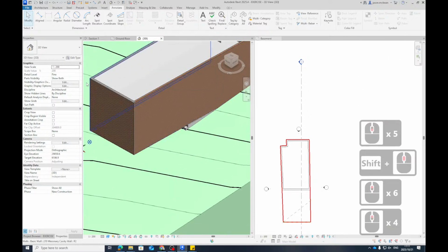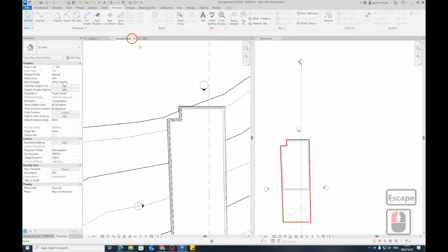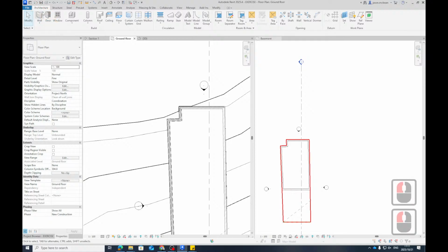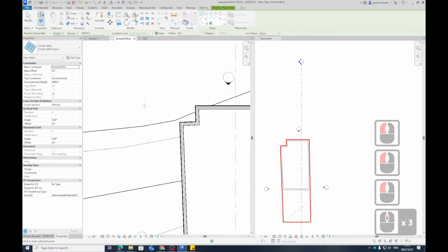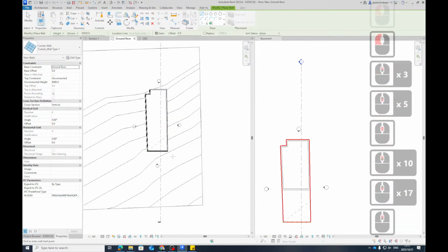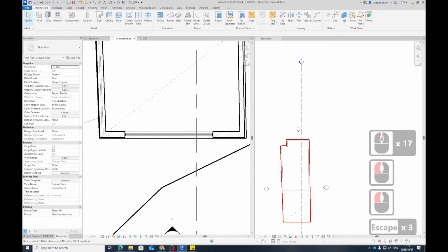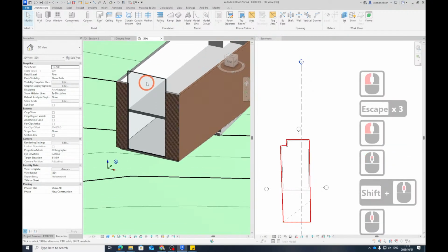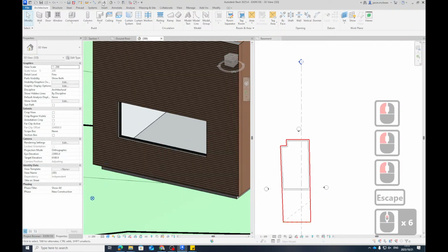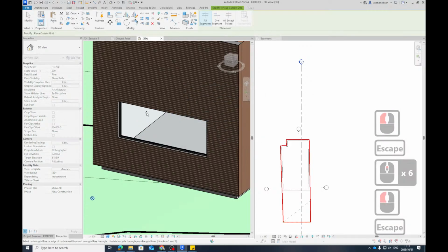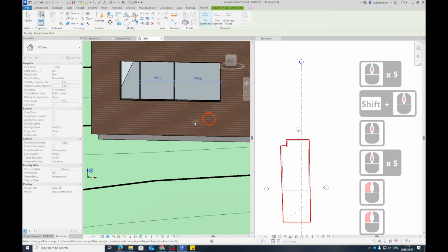Windows typically use curtain walls, embed curtain walls into your walls. Let me just show you that on ground floor. So architecture, again, you go to wall, but it's a curtain wall. These get embedded into these walls. Where's your street? Your street axis is here. If you go to 3D view now, you see that these get embedded, and you can make these into windows. So it works like a window. Then you can use this tool to add a bit more information. I would use elevation view to add more information.